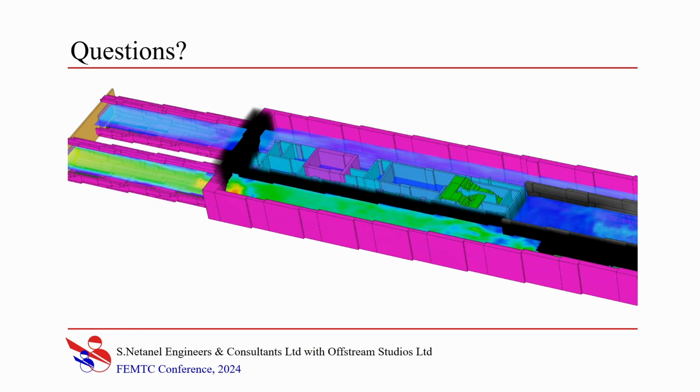So that's a good question. Obviously, I did not want any heat transfer through those boundaries. So basically, on the adjacent tunnel, we just used natural flow. And at the event tunnel, the boundaries were placed so that flow would only come in cold. Didn't want any smoke, you can actually see it here. Yeah, you can't see my screen. This is a good example of this. We want only strongly one-directional cold flow coming in through those boundaries.